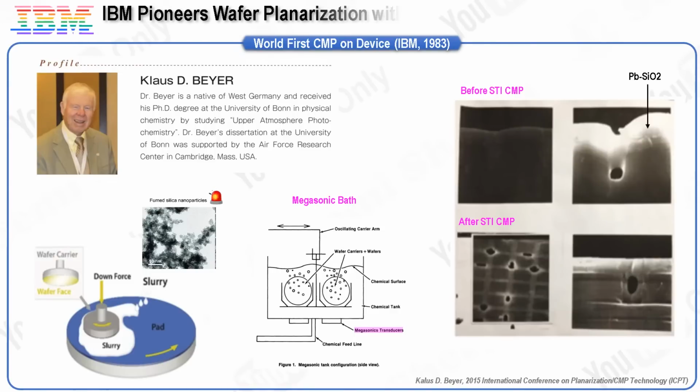As mentioned in the previous slide, the initial commercial application of CMP within the semiconductor industry focused on preparing raw silicon wafers. After slicing the wafer from a single crystal silicon ingot, the process involved removing the mechanically damaged surface layer and planarizing the surface. This was essential to achieve a flat, scratch-free surface necessary for fabricating VLSI devices and circuits. Monsanto Corporation pioneered this process, introducing polished wafers to the market in late 1962. Next, let's explore IBM's breakthrough in CMP technology.